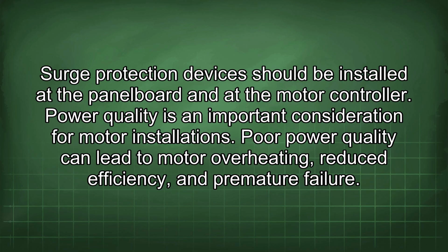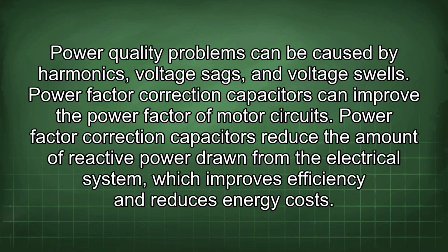Power quality is an important consideration for motor installations. Poor power quality can lead to motor overheating, reduced efficiency, and premature failure. Power quality problems can be caused by harmonics, voltage sags, and voltage swells.